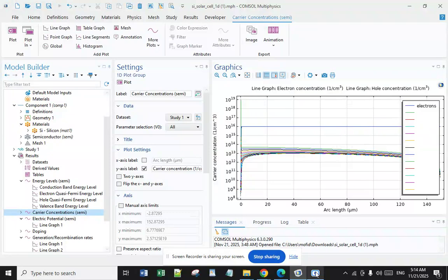Contact placement in silicon solar cells involves placing both positive and negative contacts to collect the generated current, with the ideal placement minimizing shading and maximizing efficiency. Common placements include a traditional front contact design or a passivated emitter rear contact, or PERC, or heterojunction design, where all contacts are on the back to avoid shading losses.